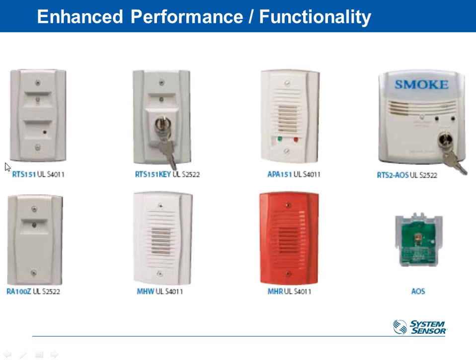The other ones that are fairly common, this RTS 151 key, that is a simple test station with a key switch. These guys are all keyed the same. The fire departments generally already have these keys, so they already know how to use them. You may be required to put those in, or you might be required to put in a test station that does not have a key and runs on a push button. I don't like those because then any Yahoo can push them. So I'd rather have the key one if it's my choice.